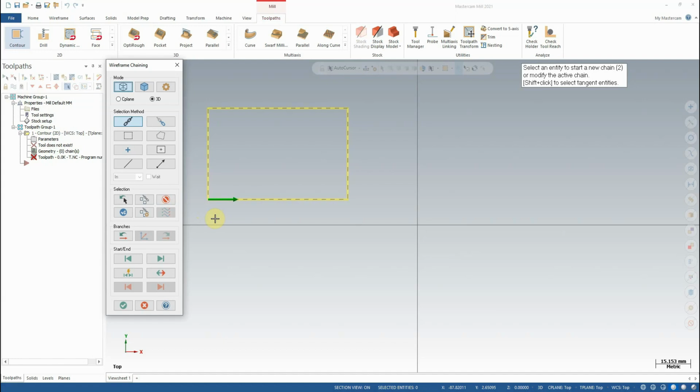Climb milling has a number of benefits. For one thing, it reduces the load on the cutting edge, it creates a better surface finish, and it improves the life of your tools. Most of these things are relevant when we're actually manufacturing products, but it is very good to get in the habit of these practices right away so that we can continue that into manufacturing.